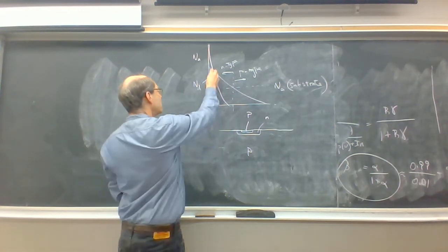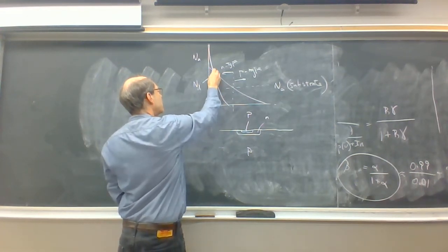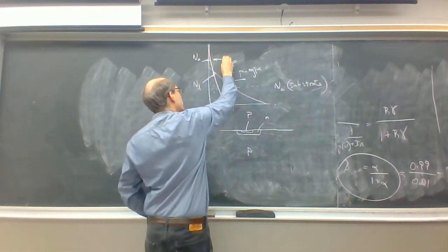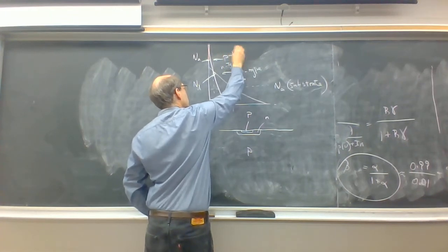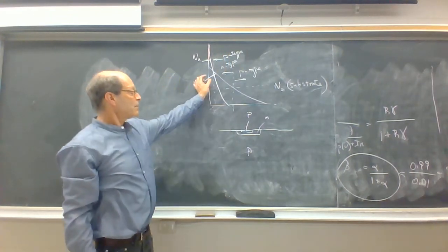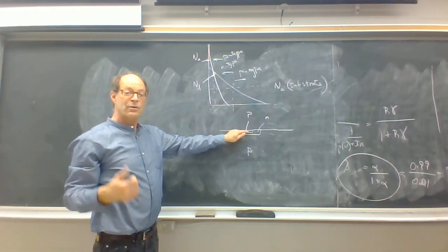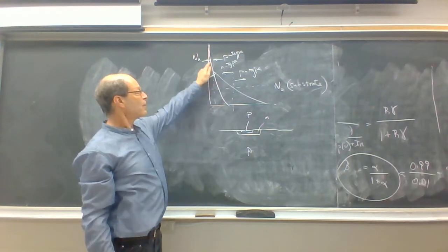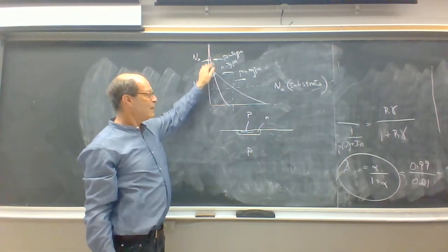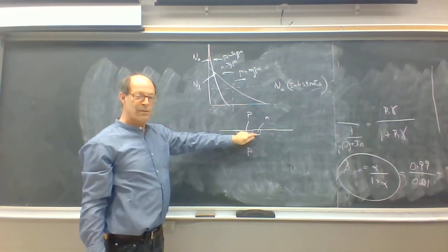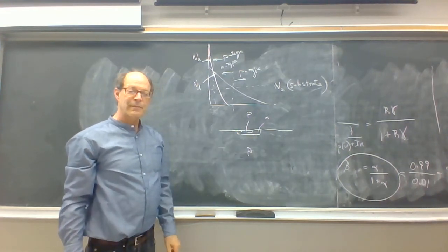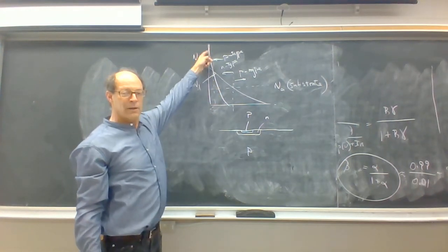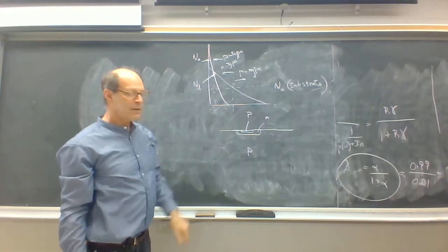So now what you can see is there's going to be another p-type region at the surface. So actually the surface region here has two sources of p-type doping, both from the substrate and from this high concentration diffused source. And it also has one dose of n-type doping, but the n-type doping is overwhelmed by the p-type doping, so it becomes a net p-type.